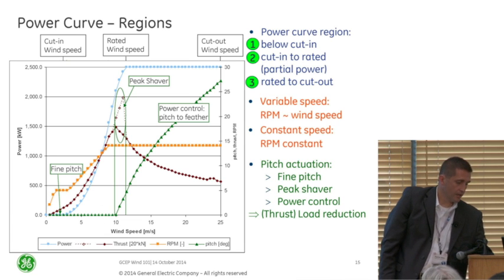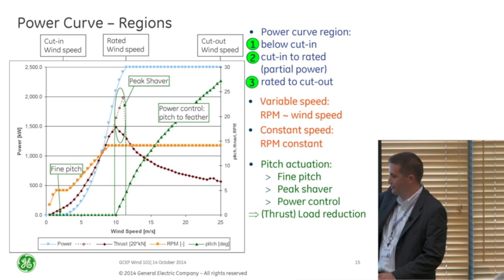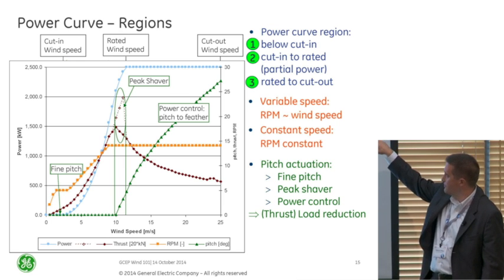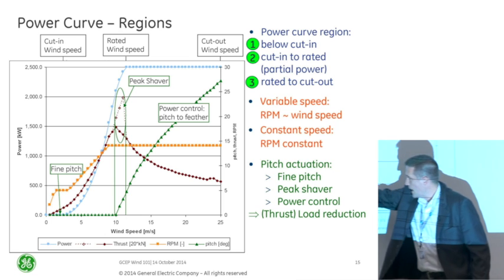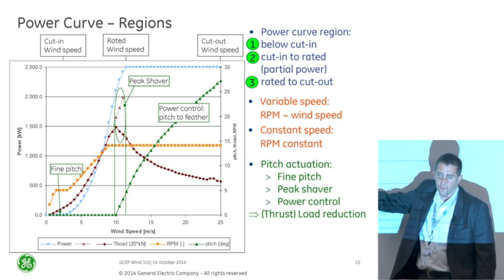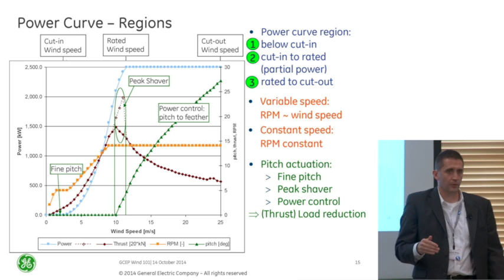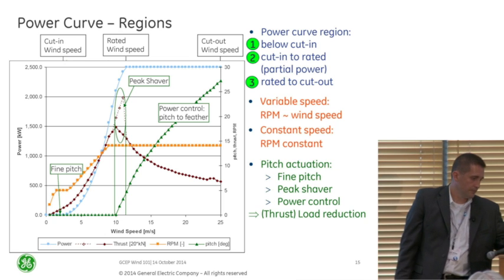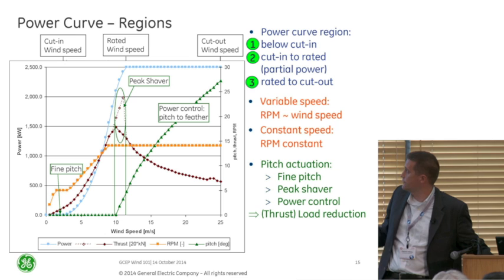Okay. All right, this is where we get into rotational speed. Very simply, I'm just going to step through this in a few different places. This is our 2.5 power curve. You see 3 different parts. Right here, no power. We're not even going to start until it gets to 3 meters per second. Then we call a cut in. We're going to start rotating our wind turbine and producing power. We go up the power curve, and then we're going to cut off.